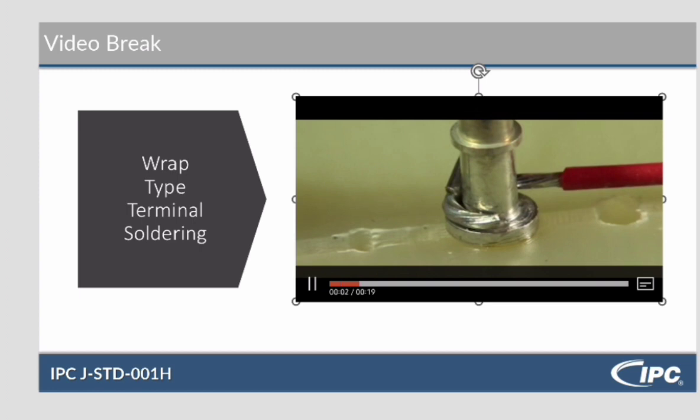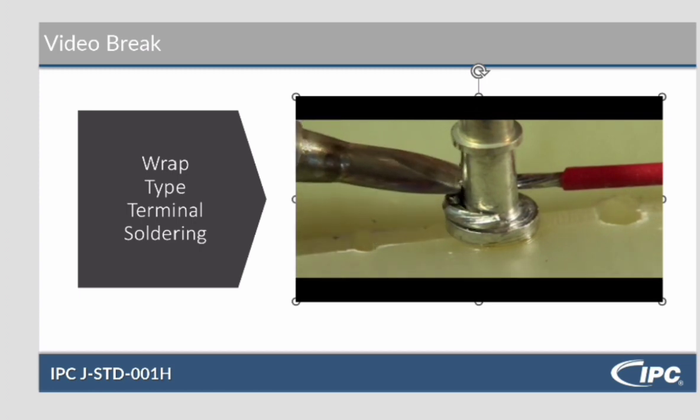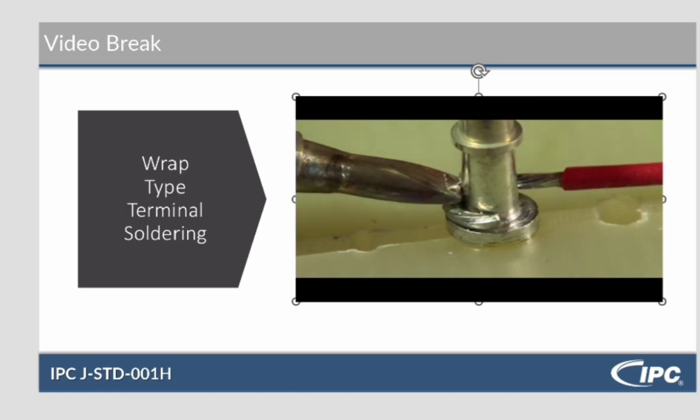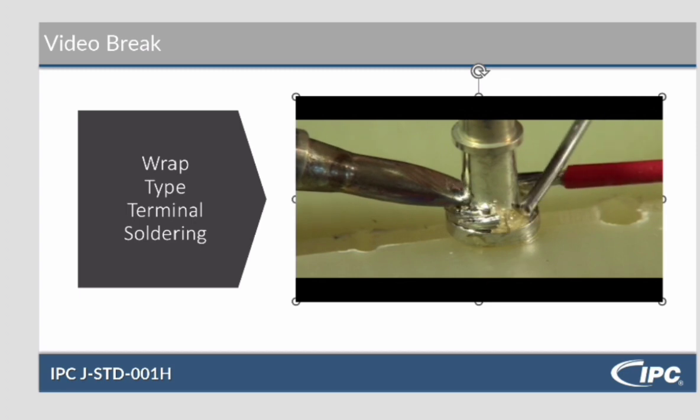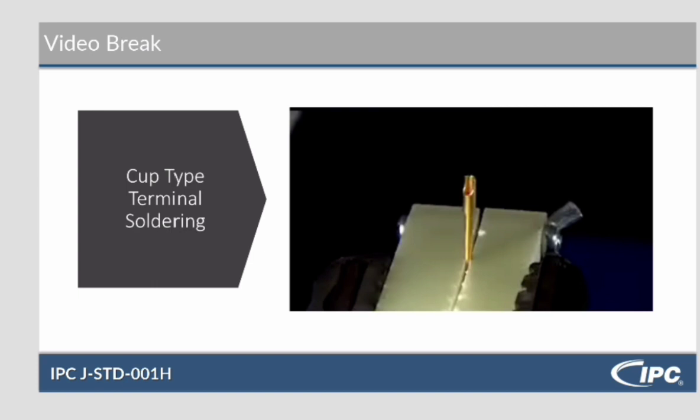A little bit of solder there to create a solder bridge. So put that solder there, touch it real quickly, put the soldering iron, get it to melt, pull that solder away, keep the iron there. You'll see that solder is flowing. You feed it in the other side. There is also flux applied here. That's what's bubbling. That is flux. It does help solder flow. Now this one, the solder cup, I love this video.